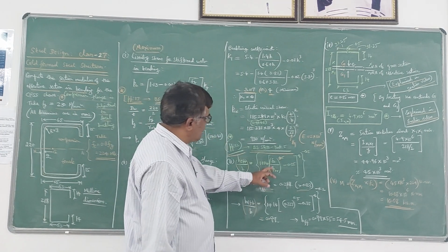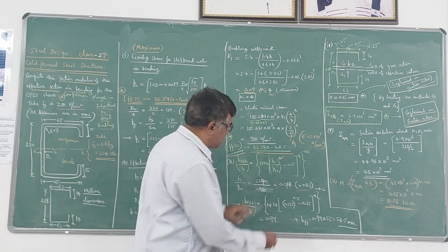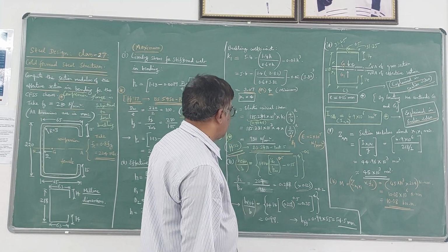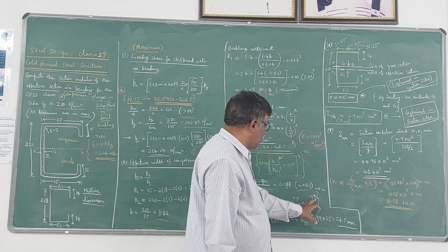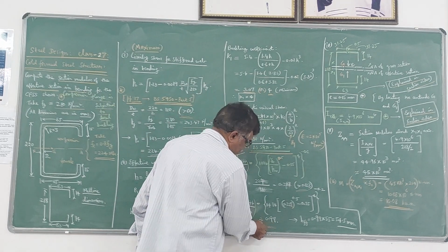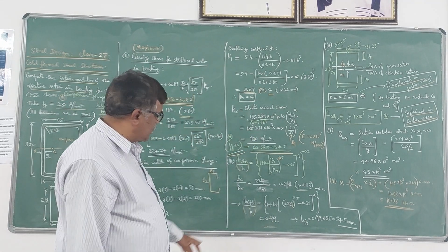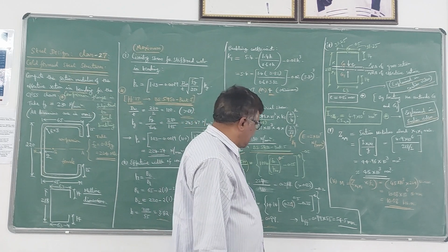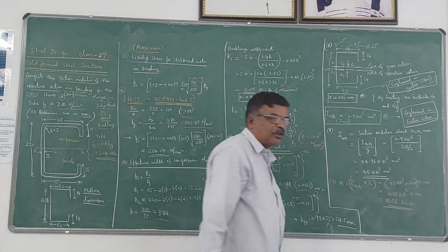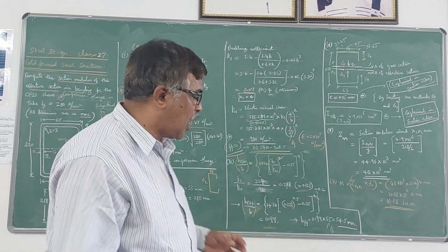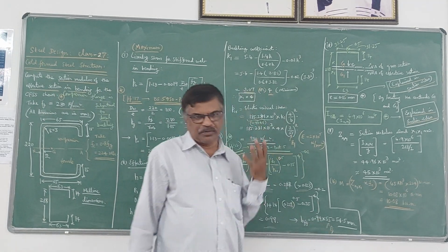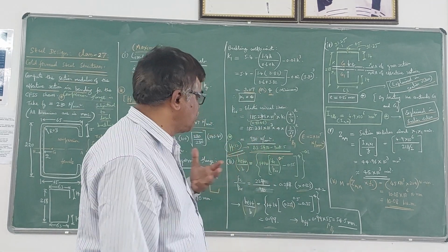Now if you substitute the value for FC by PCR, 0.228 minus this value 0.35, to the power of minus 0.2, so almost you are getting 0.99. So B effective now will be equal to 0.99 into B. B is here once again B1. So almost 54.5 mm you are going to get. That means out of that 55 mm, only 0.5 mm is ineffective. So 54.5 mm is effective.